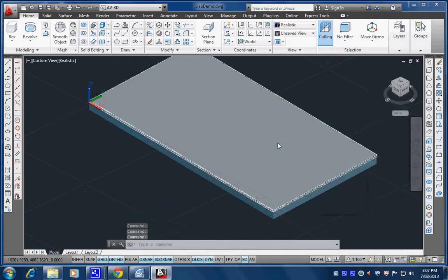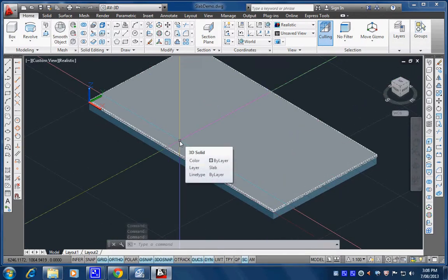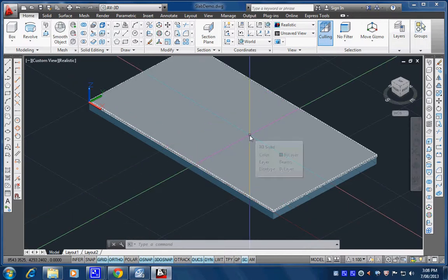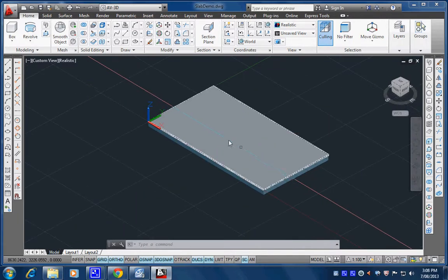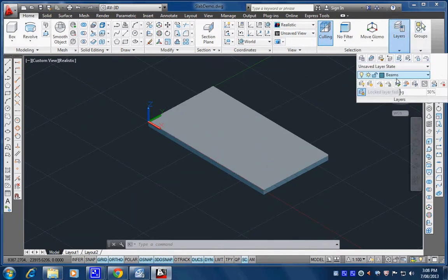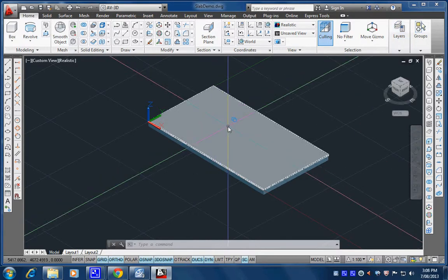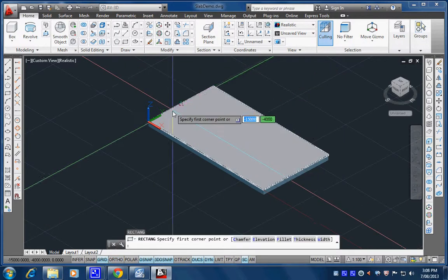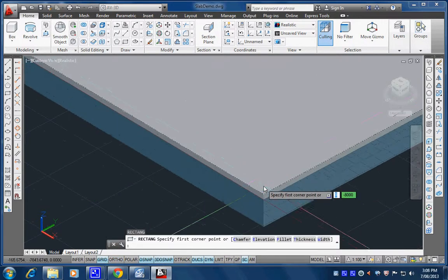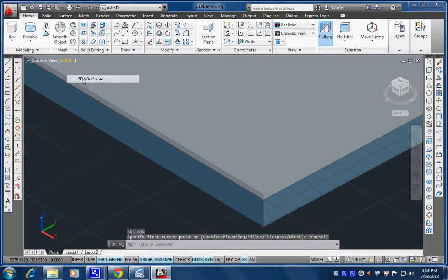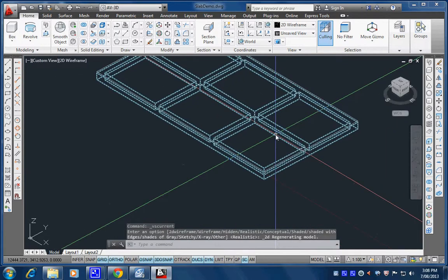All right, so now we need to put this rebate around this thing, which is 160 wide by 30 deep. So how do we do that? Good question. How do we do that? All right, let's go to the sketch here, so you can see what I'm doing. I'm going to draw a rectangle that goes from, and before I do that, I'll just change this to 2D, so we can see what we're doing a bit better.